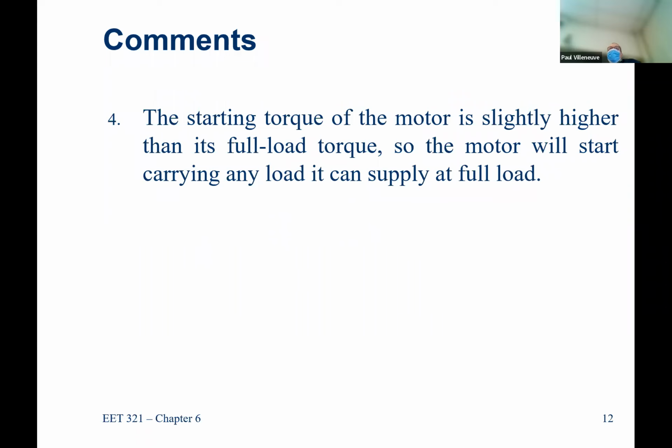Yeah, you'll actually hear it when it shuts off. You'll hear this psst, this really quick release of air, and that unloads the cylinder, because once the motor is running, it's pumping air into a chamber, and that's compressing it. If you shut the motor off and you didn't release the pressure inside the cylinder, when that motor tries to start up, it has no inertia. Now you've got a cylinder where there could be a tremendous amount of air pressure, 200-300 pounds, depending on what you set. Now it's going to have to overcome that 200-300 pounds of air pressure and push up on it.